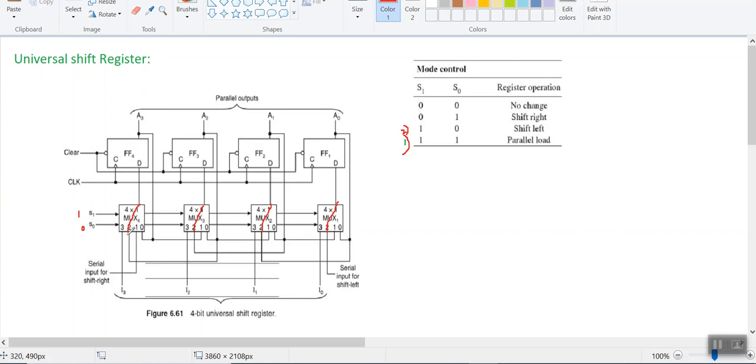For the second input pin here, we don't have any input, so you consider the input at this particular point. Your input is given here, so it goes in this direction. Say for example I again give 4 ones as my input. Initially my least significant bit 1 moves here, and you get output 1 here. Now this is connected to the second pin of the next multiplexer.